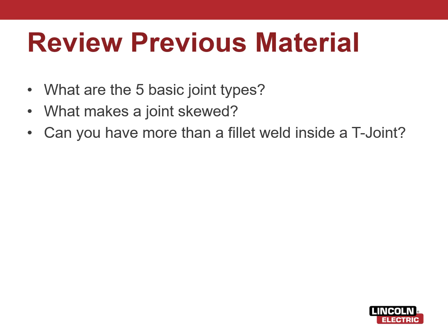And then can you have more than just a fillet weld inside a T-joint? Yes, that depends on the prep of the plate. Okay, if a T-joint is put together and nothing is done, then yes, it would be a fillet weld. But if you put a bevel on something, well, now it's a single bevel. Okay, so remember that the joint type is not the same as the weld.